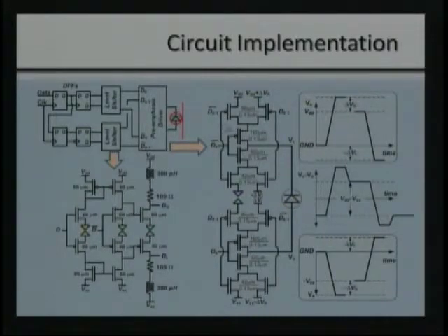When those two values are different, we pull the modulator up to a higher voltage rail than we would nominally if the two values were the same. We pull it up to VDD. And if we provide this delta VH and this minus delta VL on all four of these arms, we can produce a preemphasized waveform across the cathode and the anode of this reverse bias modulator.